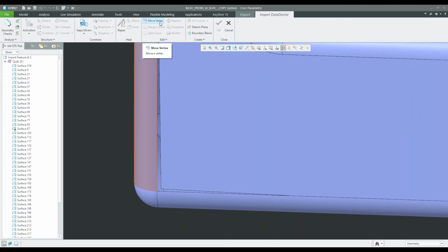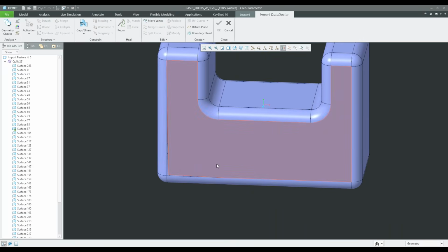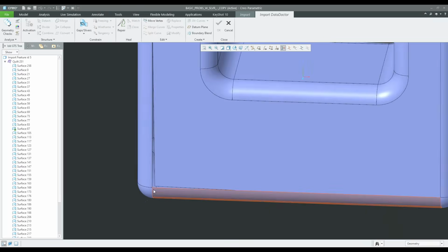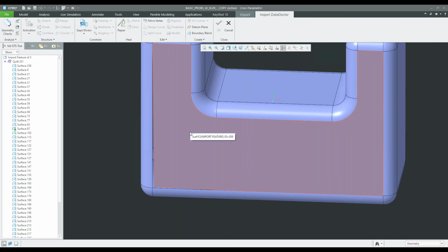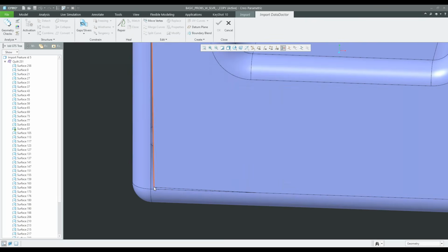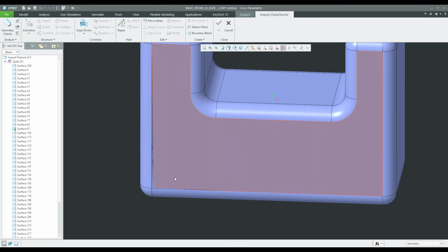And this is something that's powerful, but you want to be careful using, because if you don't have a nice clean surface, you just go grabbing the endpoints or a vertex and you start dragging a surface, it can really cause unwanted changes to a surface. So just make sure that you have a surface like this that's pretty straightforward, pretty clean, so that if you move it in this corner, for example, it's not going to cause any weird geometry inside that surface.